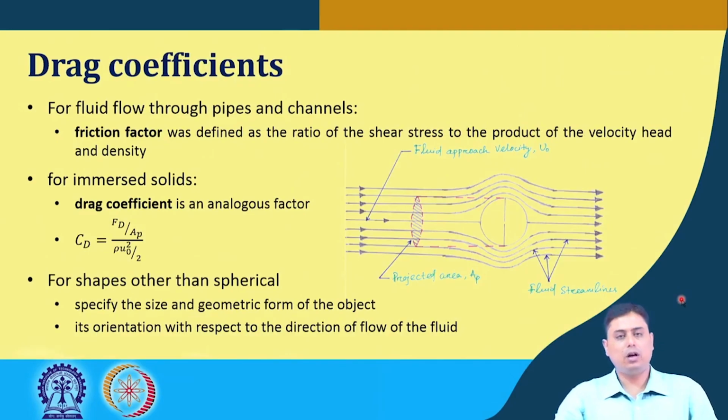The orientation of the particle we will also look at later, as I said, during screening or sieving operations, in the direction it falls on the sieve. Similarly, the orientation in which it interacts with the fluid, the fluid particle interaction happens with the particular orientation of the particle. That is also another important parameter.